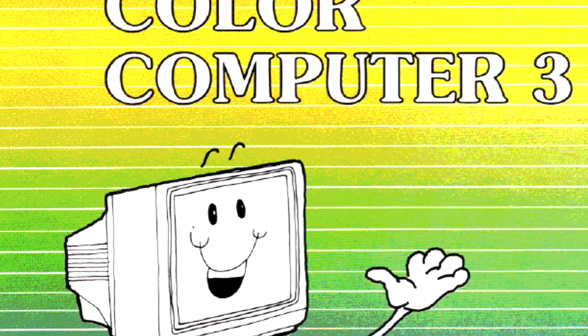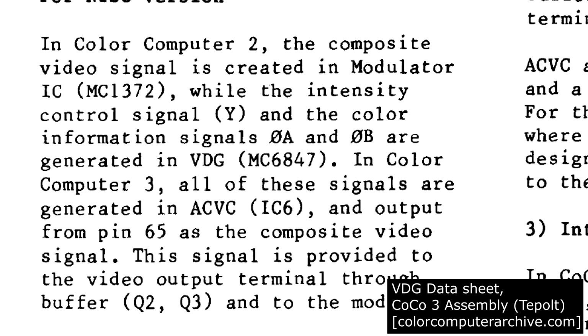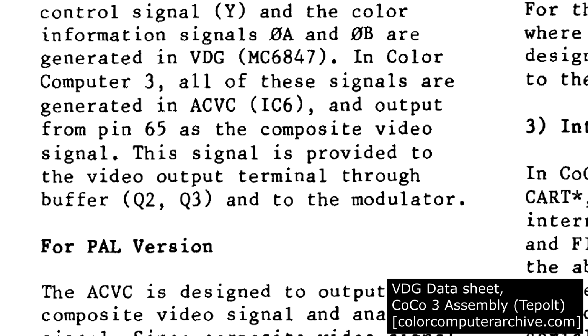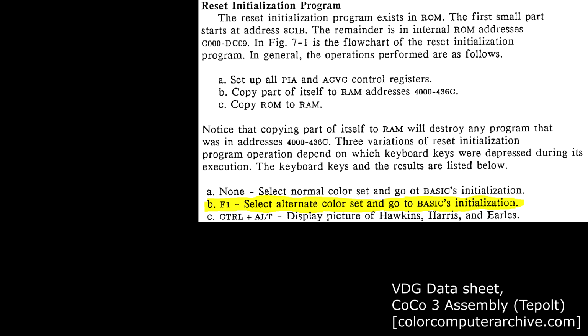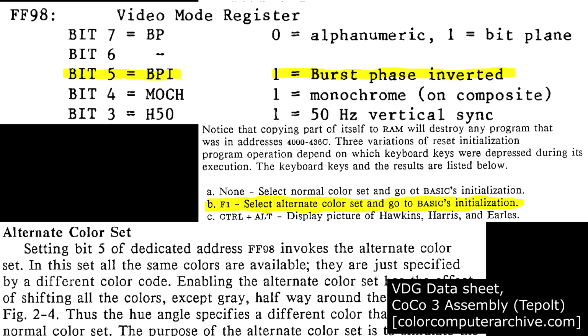Case closed. It's worth mentioning that the CoCo 3 solved this problem. Its upgraded video hardware ensures it always starts on the same clock edge. You can even change which clock edge manually by pressing a key for compatibility with older CoCo 2 software.